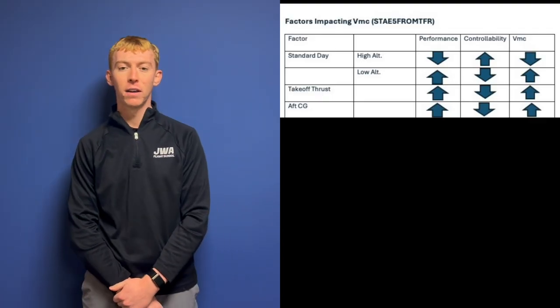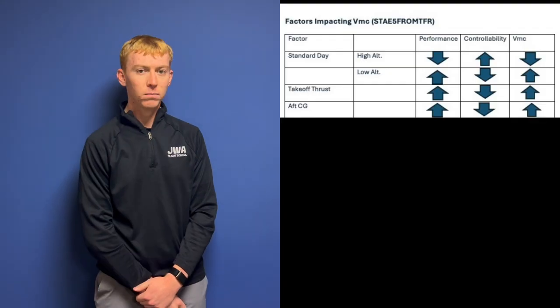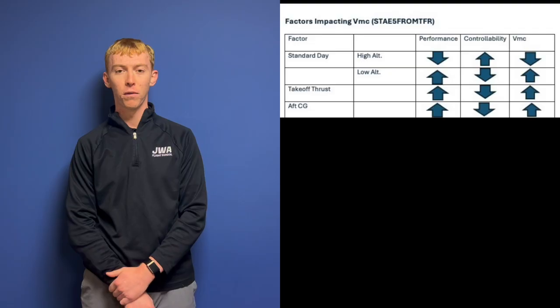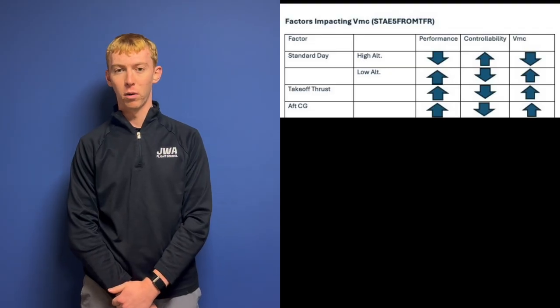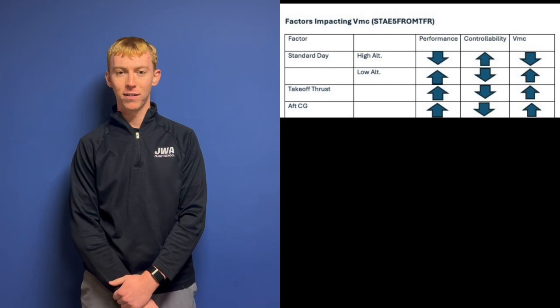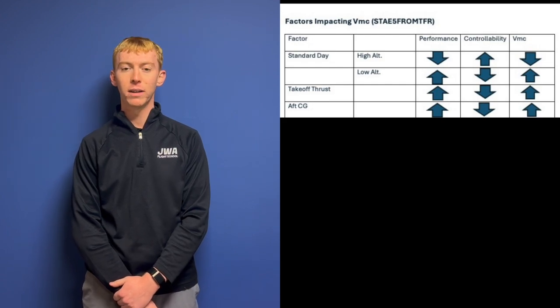Next, we have an aft center of gravity. Remember back to your commercial check ride. With an aft center of gravity, performance is better. Why is performance better? We have less drag on that aircraft with an aft center of gravity. Controllability, however, is going to decrease.